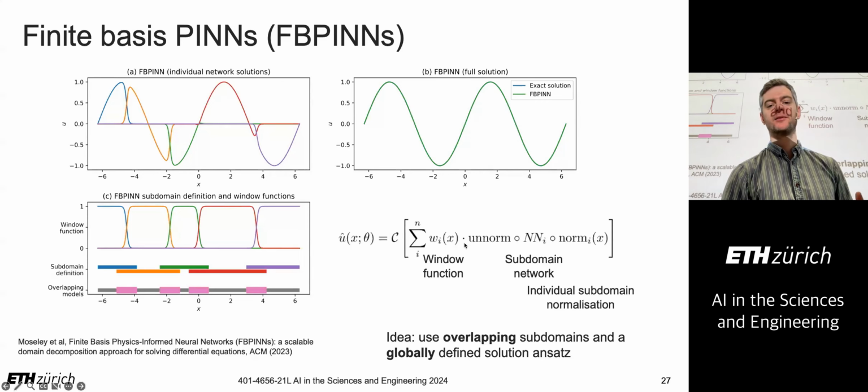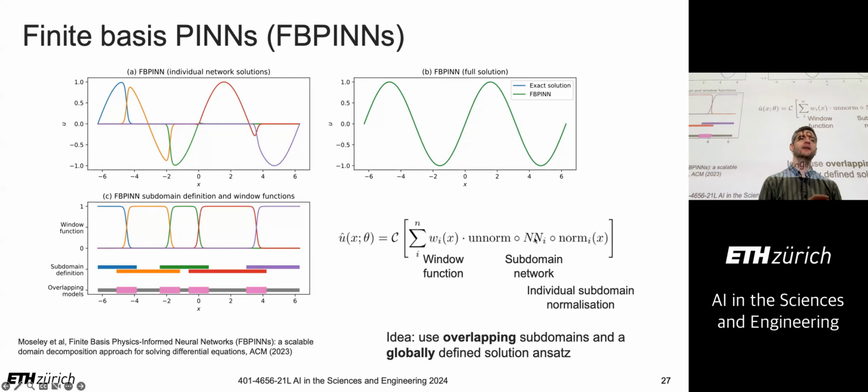That's exactly how you interpret this. You say my neural network is now learning that basis function, rather than the basis function typically being a polynomial or a tent function or whatever you want to choose. I really like that interpretation, because then you're starting to have a unified understanding of FEM and how FEM relates to PINNs, for example. A standard PINN is like FEM with one element and a really big basis function. That's the way to think of it.